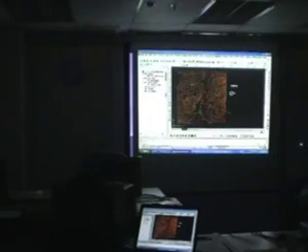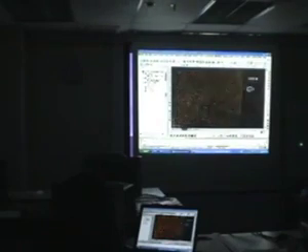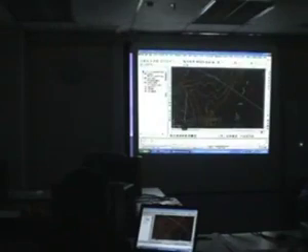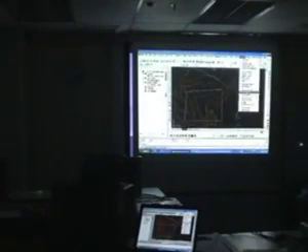I'm going to create a proposed level here, like a platform, so that we can run our volume calculations. I'm going to zoom into this blank spot. Okay, and I'm just going to draw a line from here. Not sure what level this should be, so let's say I just want to check what is the elevation of my existing ground.